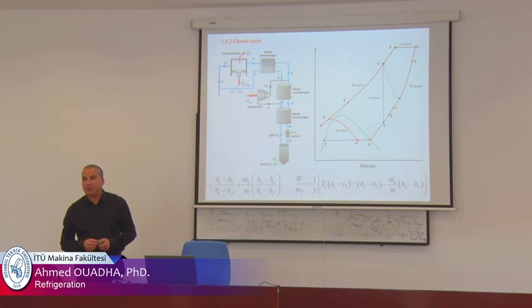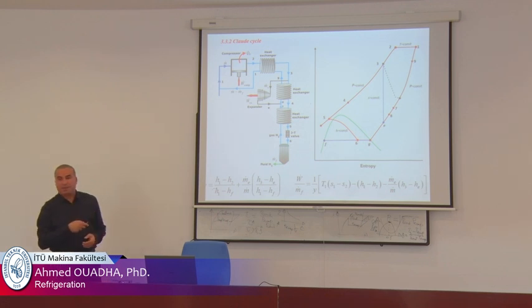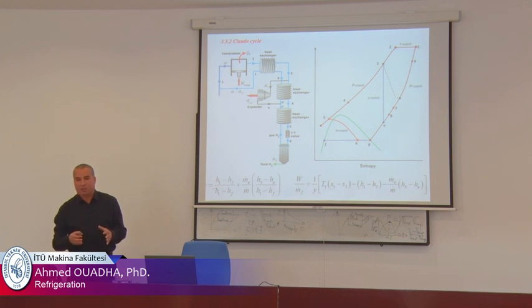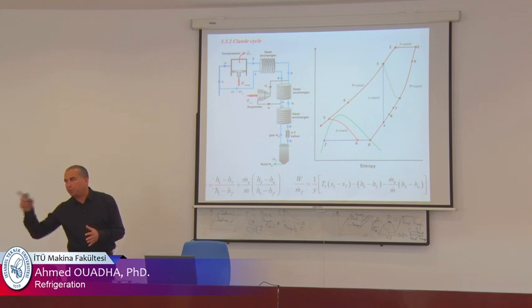Yesterday, someone called Morat wrote to me on LinkedIn. He is working in the Netherlands; he did his study here. He was working on a ship, and they use a reliquefaction system on board ships. You know that when we transport liquid in tanks, some of the liquid evaporates naturally. So we remove the vapor, reliquefy it, and return it to the tank for safety. Because when there is evaporation, the pressure increases, and the tank is designed to support a certain design pressure. So this system is used on board ships to reliquefy the boil-off of LNG and return it to the tank.